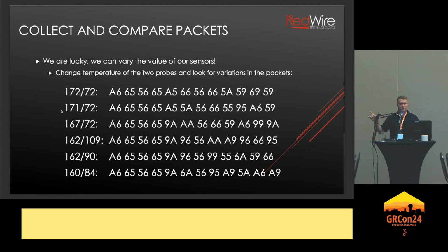But I ran into a little trouble here, and I don't know if you can notice the pattern to all that data up there. I only ended up with hex values of A, 6, 5, and 9, which looks a lot like Manchester still, which led me to think maybe something was wrong with the block. I went back through my block, and it appears to be demodulating. I went so far as to print off the time domain plot you saw there and decode it by hand. Sure enough, this is what you get out of it, which left me a little confused.